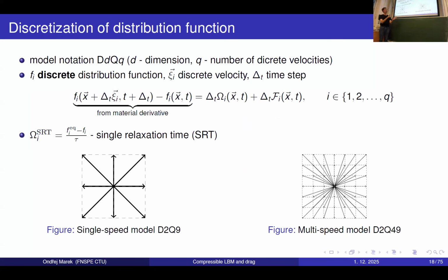So for the domain and the time, we just discretize it into time steps, delta t here, and the domain is now discretized into a uniform grid. That's the specification of the Lattice Boltzmann method, because when we discretize the distribution function f, we have the whole velocity space, which we need to somehow represent. So we represent it at some points here, even though it's not seen that clearly.